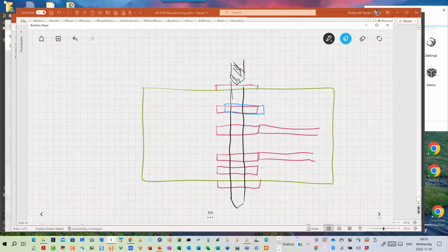Since this would be a core, this layer's offset, and then what if this layer is offset the other way too far? As I'm drilling through this one right here, this is okay because the trace itself will extend over here, or the plane layer, or whatever I'm connecting to. Same thing right here. I have the trace connecting, so I'm okay.